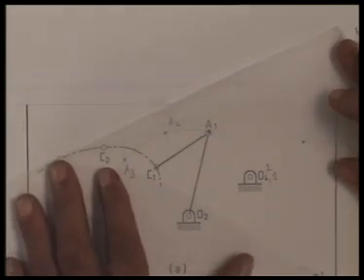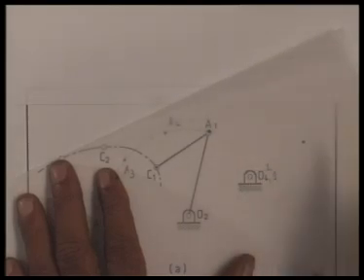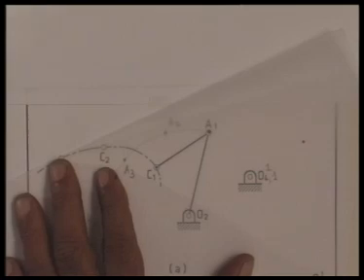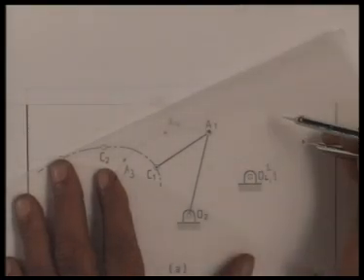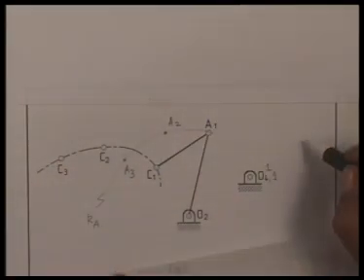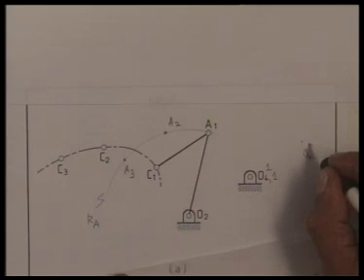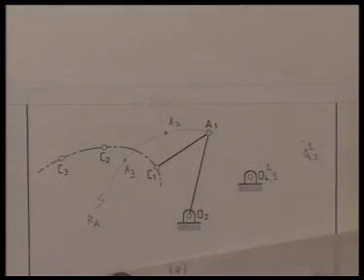A2 with A1, C2 with C1, and as we see, O4 moves here. So we mark this point on our drawing sheet. This point we call O4, corresponding to the second position but inverted on the first position. We call it O4 2 1.